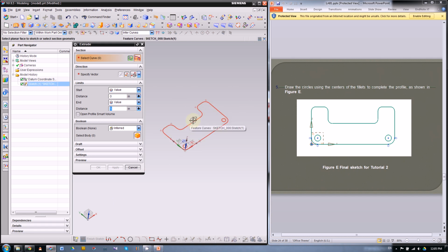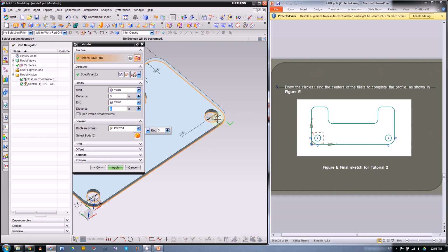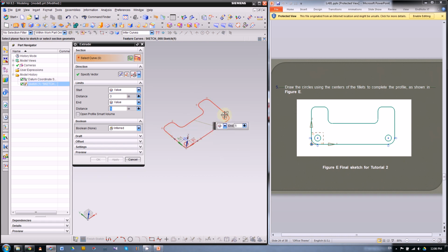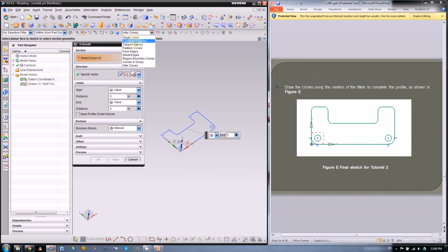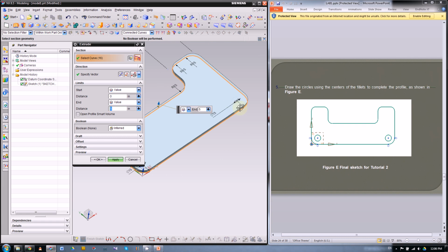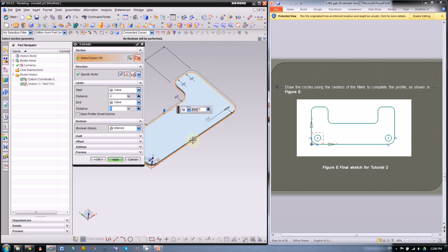Okay, you can pick this curve. Invert curve will give you all the curves, I think, with these circles. And I'm going to deselect this and show you what happens to the connected curve. And deselect, select window, press Shift, and click. Okay, it's deselected. And you can use connected curve and pick this. See, there are no holes here. So there's some flexibility. You can choose to extrude without the holes or with the holes.